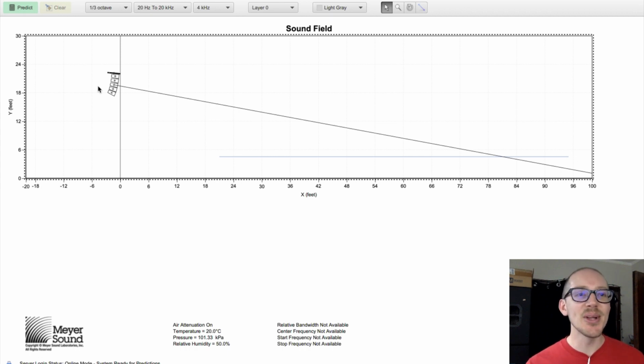Okay, that's my goal. And I feel like if the front to back ratio is less than 6 dB, then it's probably better not to do anything and just leave the array alone. The other thing that's tricky with small arrays, I've found, optimizing them in these rooms, is that a lot of times the gain shading doesn't do anything.